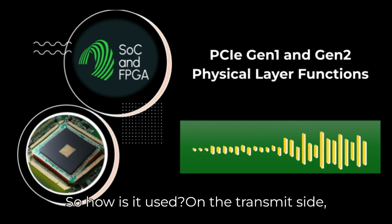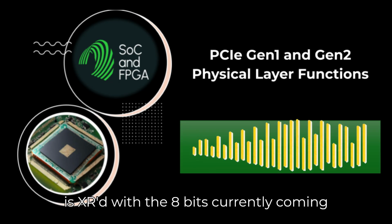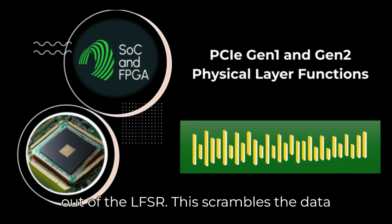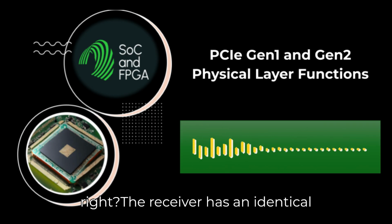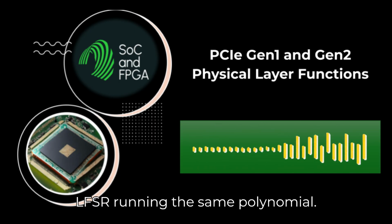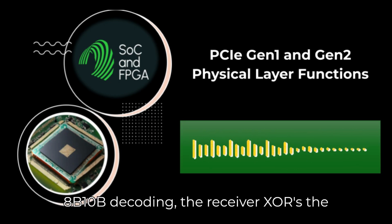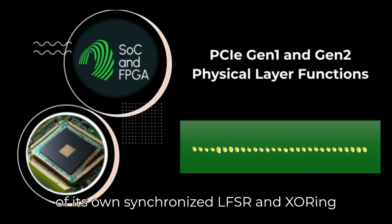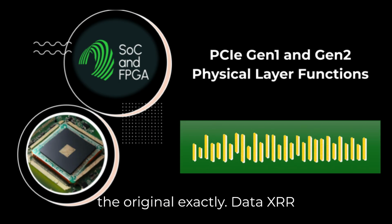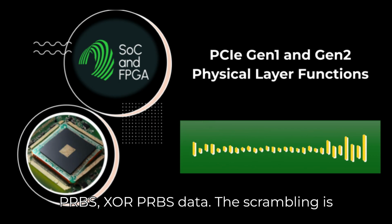On the transmit side, each 8-bit data byte before 8B10B is XORed with the 8 bits currently coming out of the LFSR. This scrambles the data. XORing with a pseudo-random sequence. Right. The receiver has an identical LFSR running the same polynomial. Crucially, it needs to be synchronized with the transmitter's LFSR. After 8B10B decoding, the receiver XORs the incoming 8-bit data byte with the output of its own synchronized LFSR. And XORing twice with the same value gets you back the original. Exactly. Data XOR PRBS, XOR PRBS, data. The scrambling is reversed. Clever.